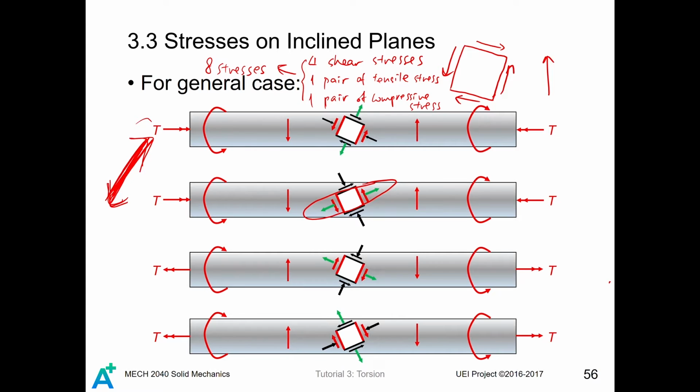And similarly, for the positive torque, you observe that on the right hand side there is a negative shear stress transmitted through the length until it touches this face, which is much better aligned to this vertical shear stress. Therefore, for this surface, we call it the dominating surface.